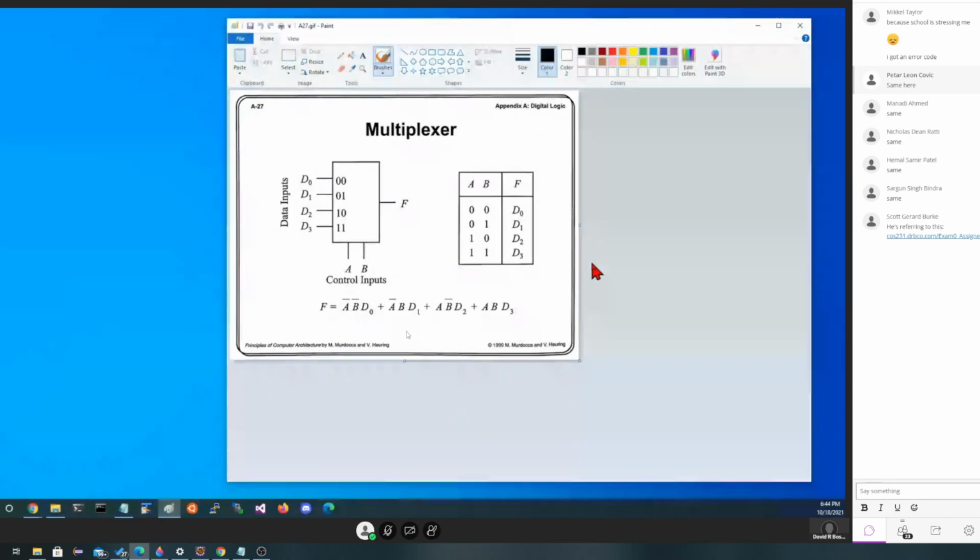So let's look here at a multiplexer and how we might use it. First of all, the square box is going to represent a multiplexer. Now, we know we could build one out of NAND gates if we needed to, but we also could out of ANDs and ORs and NOT gates, or more sophisticated, we could just buy a TTL, a multiplexer.